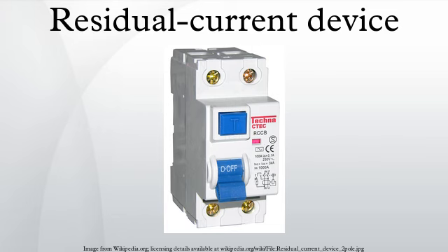Rated current. The rated current of an RCD is chosen according to the maximum sustained load current it will carry, so generally if the RCD is connected in series with a single fuse or circuit breaker, the rated current of the RCD shall be at least the same as the fuse or circuit breaker, though in the case of an RCD feeding many circuit breakers, an allowance for load diversity may or may not be permissible depending on the type of load expected.